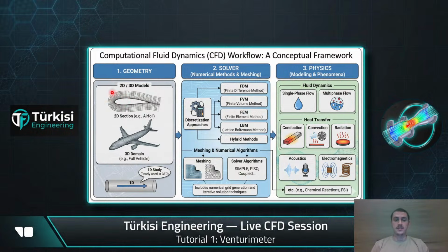You have air, but where you stop your air domain, you need some enclosure, like a wind tunnel. Think about a wind tunnel. You should have a tunnel to understand the maximum distance that the airfoil's disturbance in the fluid domain affects. So you should enclose that area and include it in your 3D model or 2D model. This basically explains some ideas of geometry.